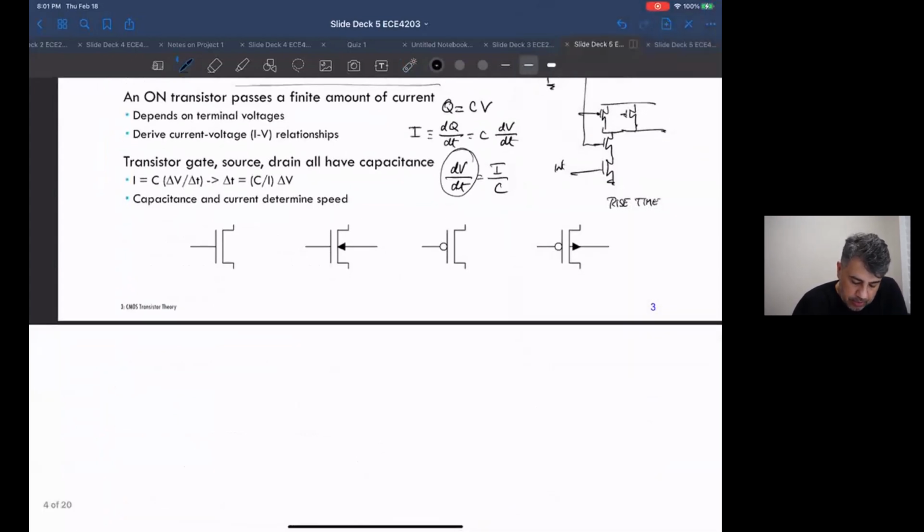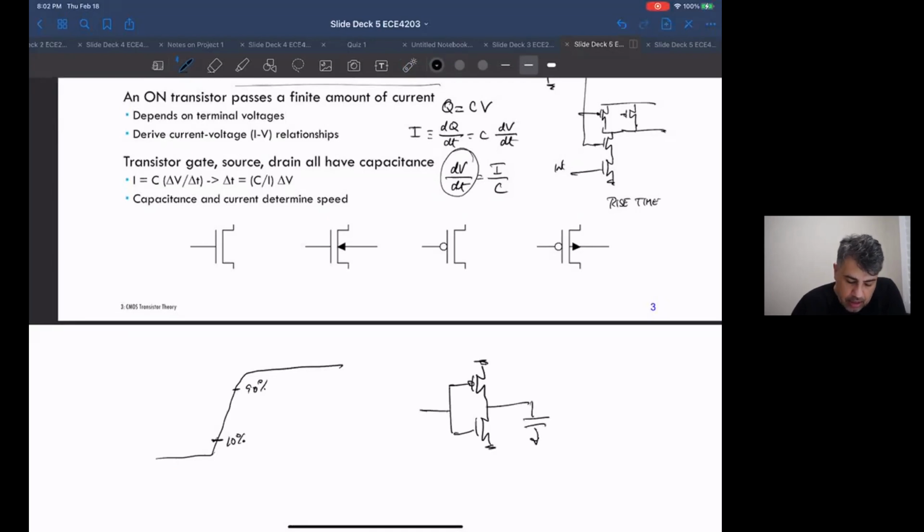Let's think about the rise time. So we said the output has this 10% to 90% transition that we're looking at in problem 2 of the project. So if it was a CMOS circuit, let's say I'm driving another 4 inverters like myself. I'm just going to draw them as logic devices, but they just look like myself. So this is an FO4 fan out.